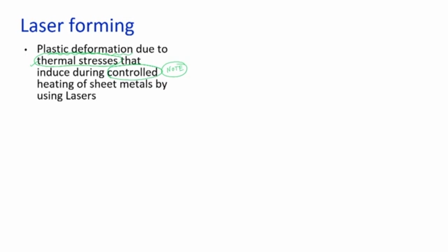That is not desired, and it has to be very carefully taken into consideration when we apply the process parameters. The lasers are to be applied with power and speed in such a way that there is no melting, only pure deformation without melting. Then only can we generate a good quality deformation by using lasers.